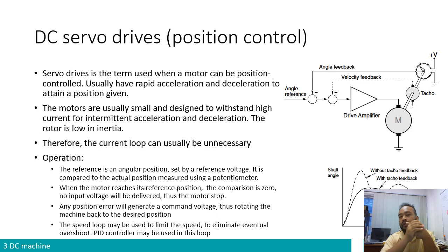And then secondly, we have looked at the chopper or PWM driver. And then in control, we have looked at the usual feedback, speed and torque control embedded. And then we have looked just now at the addition of servo drive, which is basically a position control.